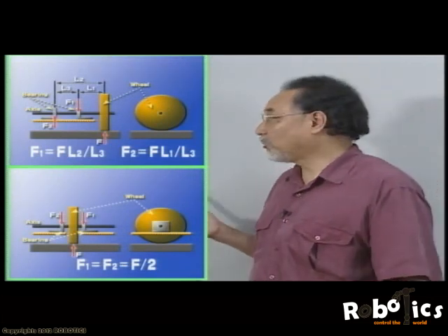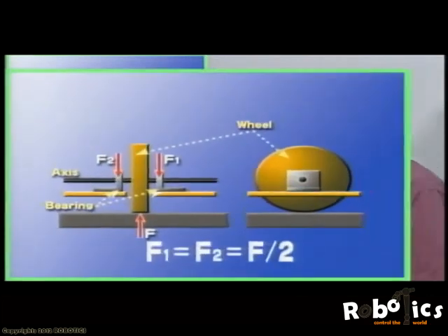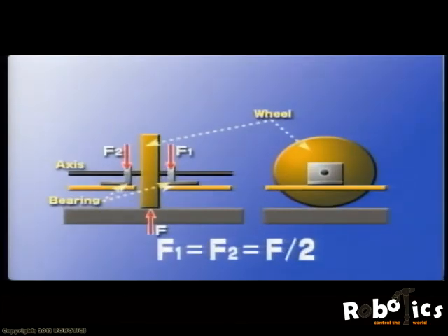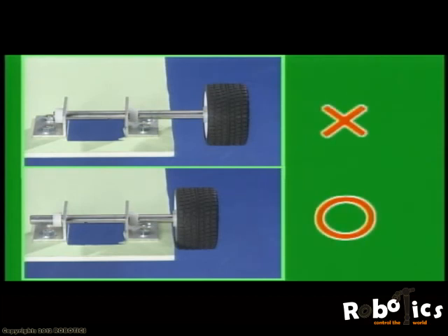This test demonstrates how important it is to reduce bearing friction. When building your machine, use this ideal design if you can. If you have to use single-sided support, minimize the distance between the inner bearing and the wheel, and maximize the distance between the bearings.